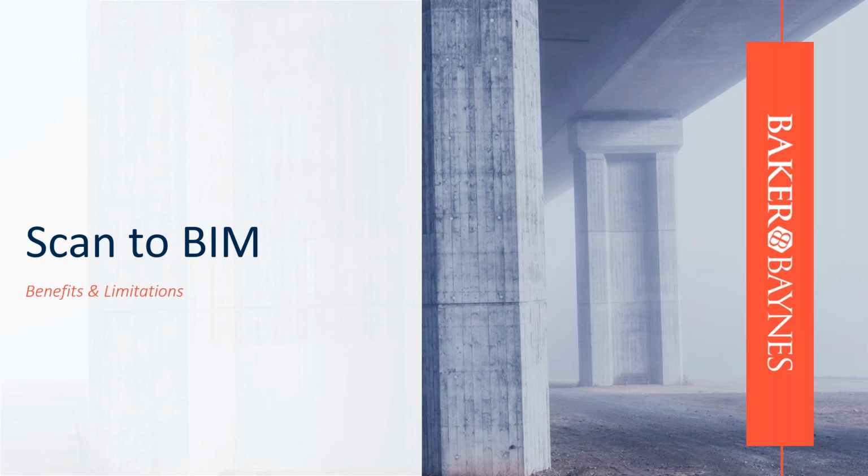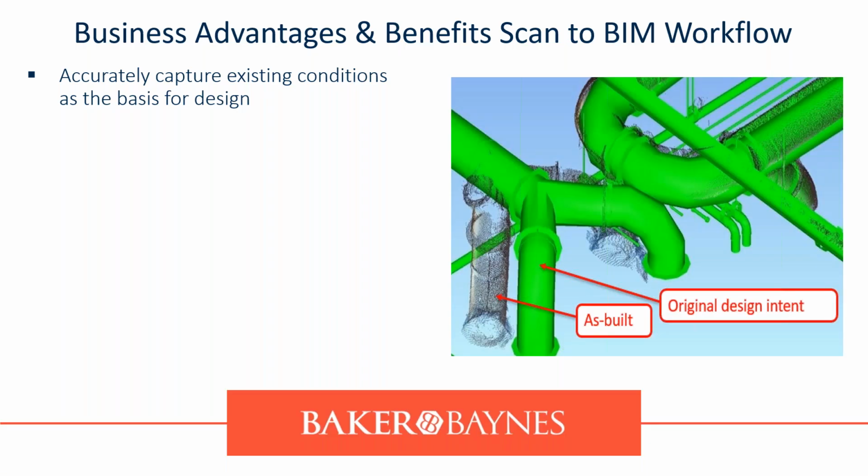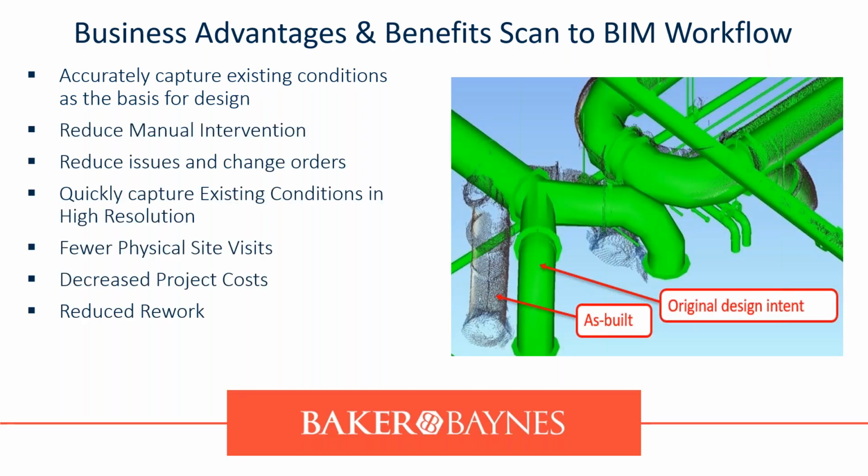Benefits, you just need that actual image on the right-hand side to get a picture of it. But if you look at this, you could take your model, do a scan, and overlay that point cloud scan over your model to see what was built versus design. As you can see, this pipe is sitting there, constructed after design or after sign off or handoff, but on your original design, it was sitting here. You can now update this model so that it matches the point cloud and it makes your life much easier rather than scanning, modeling, remeasuring from scratch and taking it in.